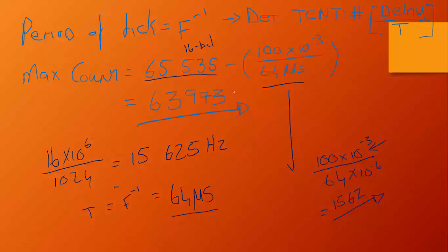This is your timing byte, and that is what you load into the appropriate register, because it's from this point that it will count onwards. It just keeps incrementing, counting 1,562 hits, until it reaches 65,535, and then you get the overflow.